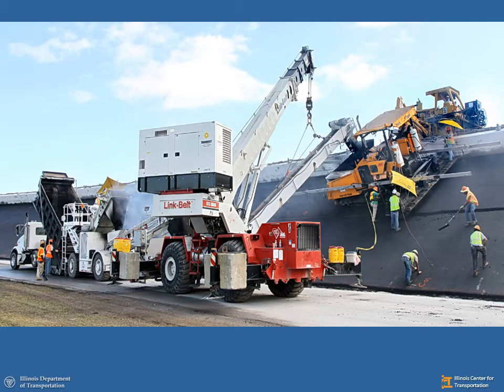Challenging. Talk about challenging. Yes, here we go. We got almost a 45-degree bank. This is Daytona Speedway. Here's my delivery truck with its HMA in there. We're dumping into the hopper of this material transfer device. Here's the arm of the material transfer device, which is held up by a crane, dumping into this paver that's on this 45-degree bank.